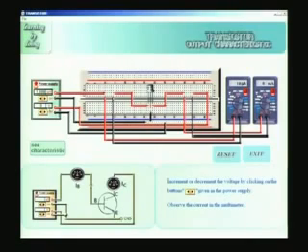Now I am going to vary the VCC supply, which is at the bottom, continuously in steps of, let us say, 0.5, and see what happens to the collector current. I am going to keep IB, the base current, constant, and vary VCC, and for every value of VCC I apply, I will measure the collector current. Now let me increase: it is 0.5 and it is now 0.1 milliampere IC. Now it is 1 volt VCE and it is 0.5. At 1.5 it is about 1 milliampere.